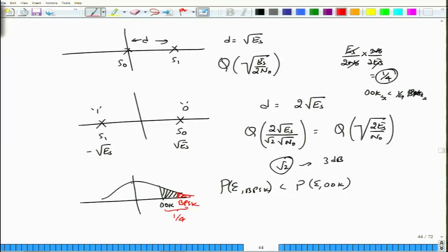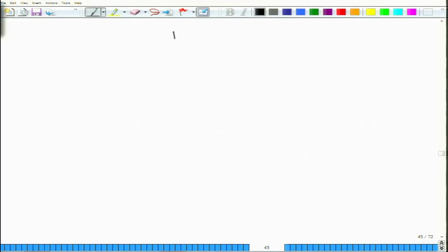This is the Gaussian distribution that we have drawn as a function of noise here. So, clearly BPSK systems are performing better than the on off keying system. You can extend this BPSK system into additional modulation schemes such as this one, which is called 4 QAM, or you can also consider 4 different phases here.